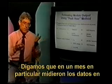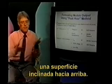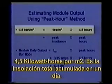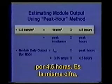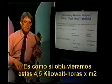Let's say that a particular month you have measured data on a tilted surface, and in a particular location for that month, let's say 4.5 kilowatt hours per square meter was measured. That's the total amount of insolation accumulated over a day. We can rewrite that as 1 kilowatt per square meter times 4.5 hours. It's the same number. But what is 1 kilowatt per square meter? That's 1,000 watts per square meter. That's peak insolation.